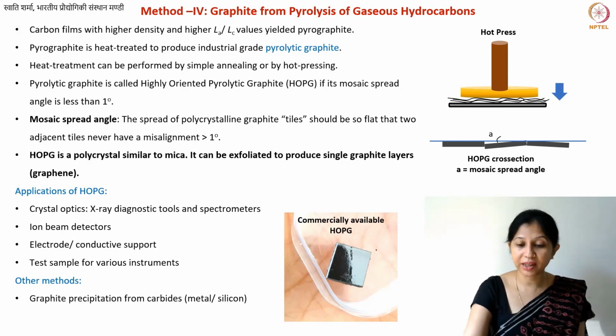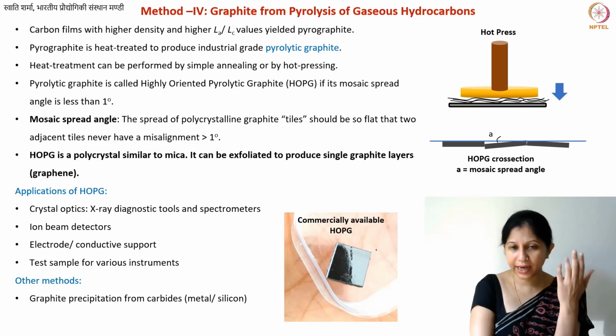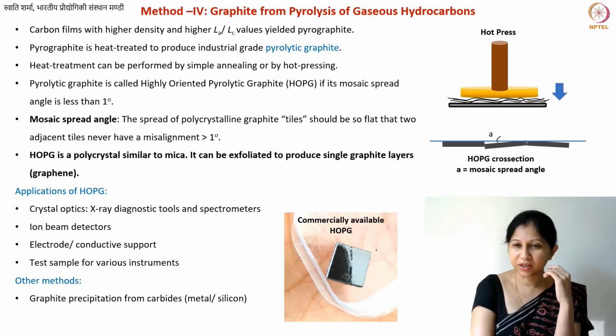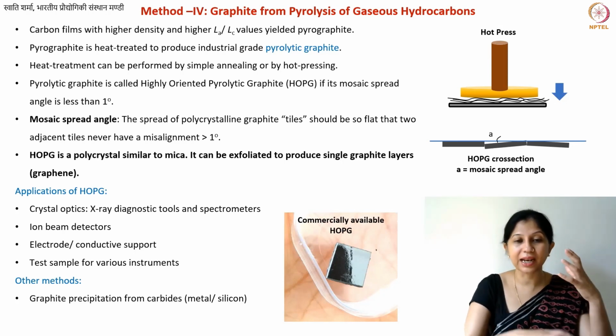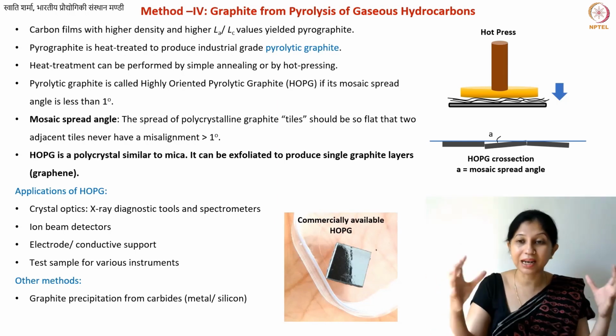I need to also mention that there are some other methods where you can get graphite, which is known as catalytic graphitization. So when you're collecting your graphene sheets during CVD, that also has a catalytic support, right? So metal catalysts are always helping the growth of carbon materials, or providing an orientation to the carbon materials. Now, in this case, what you can also do when you're making large scale graphite, so you're not making a certain type of sample, but you're making bulk graphite,